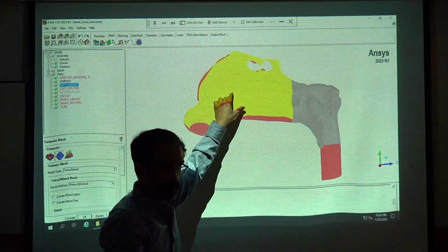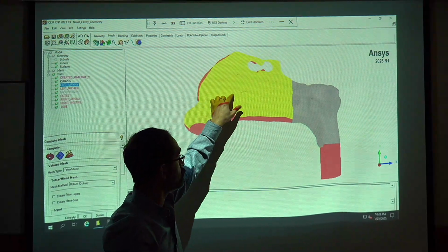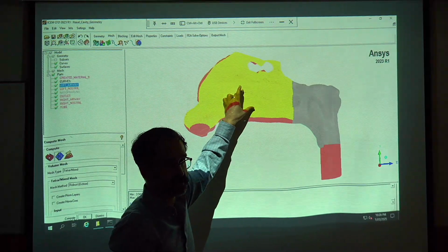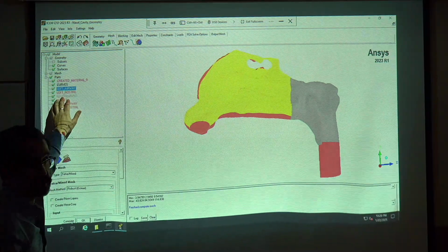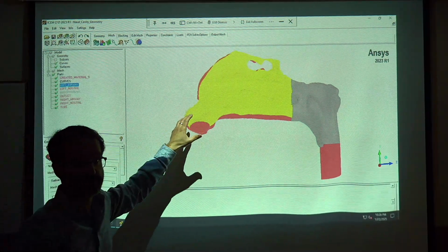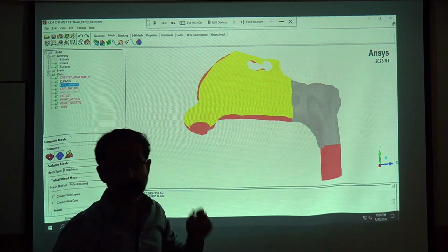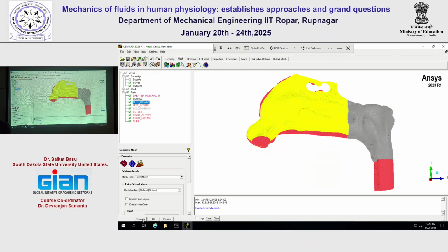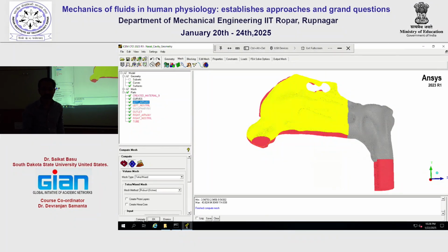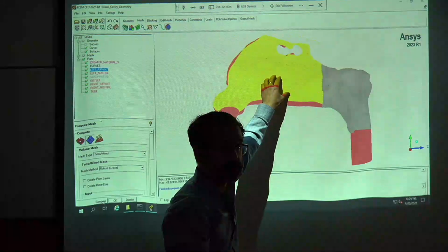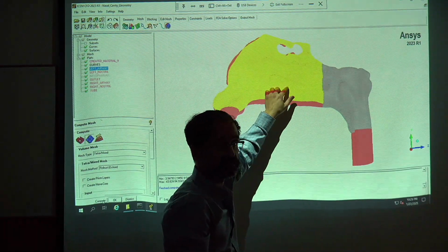So you have to get the geometry into ISM, draw out a curve, and there is a way to do region partition. You develop that particular region, name it to show up over here, and then that would show up on your Fluent simulation as well. And you can directly get the deposition amount for that region. So for example, when I was doing some more clinical studies where we were trying to figure out drug delivery for sinus inflammation, the target site is actually here, because if you think about the different sinus cavities, they are draining their fluids right over there. But then we have to develop a region right over here.